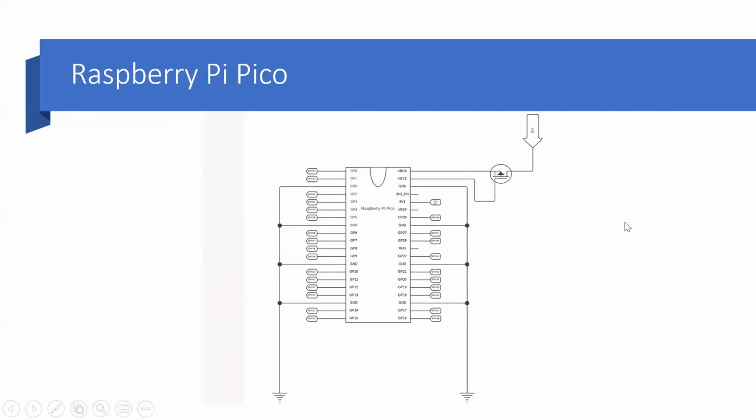So this is the Raspberry Pi Pico. It has all the GPIOs called out here. And it's powered directly from 5 volts. And this MOSFET here will allow us to debug in circuit. So you can plug in the USB. It will take whichever voltage is higher, either the 5 volts from the power supply or the USB, without damaging anything.